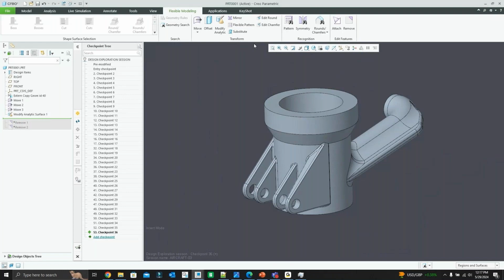So I'm hoping that you guys saw the power of the tool for 3D printing. Even though you have your parametric model, you can export that parametric model as a STEP file and then tweak that in the flexible modeling extension, or you can convert the bodies to parts. And if you want to remove the association between them, you can do that. So the main thing is that you have a separate set of parts that aren't parametric that you can tweak for 3D printing to accommodate changes in the geometry from temperature, and the different printers that you're using.